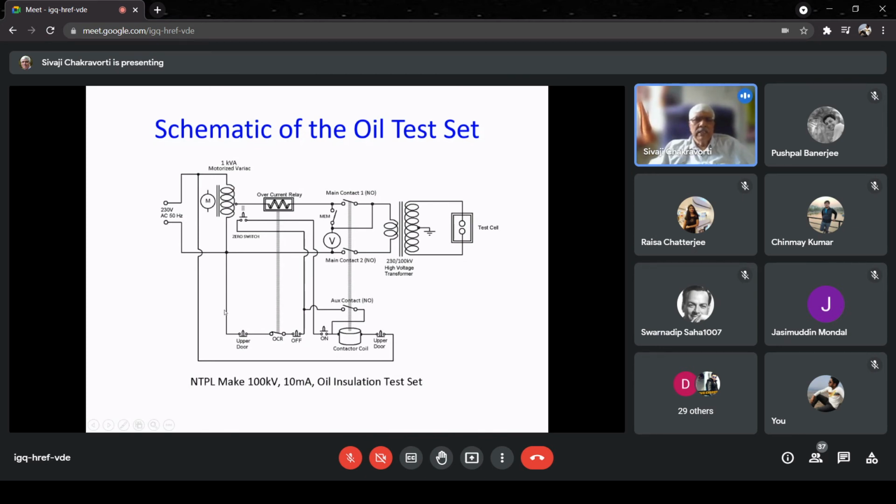And how this control circuit works, these are all done through contactors. Our primary objective is to either energize or de-energize the contactor coil. Now, the on switch is in series. We call it normally off, an NO contact. When you want to switch on, we press the contact and the circuit closes. Then there will be an off switch in series. It is normally closed, we call it NC. So normally the circuit is closed. When you want to switch off, we press it, and the circuit gets disconnected.